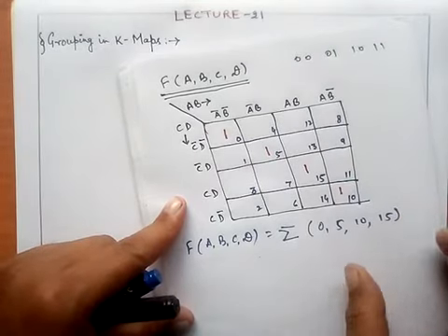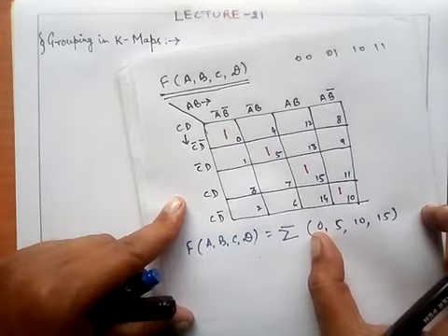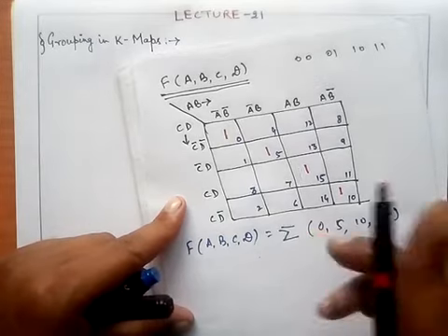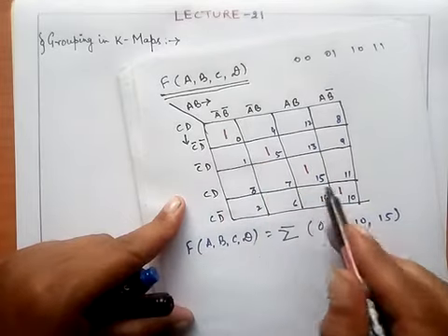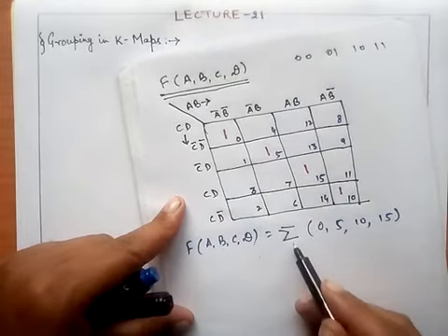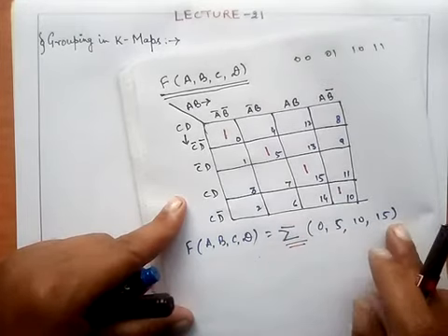The first step is that whatever min terms are provided to you, whose decimal equivalents are given, the very first thing is to simply introduce a 1 here. Simply substitute a 1 on these positions for sum of min terms. This sigma is the sum of min terms.